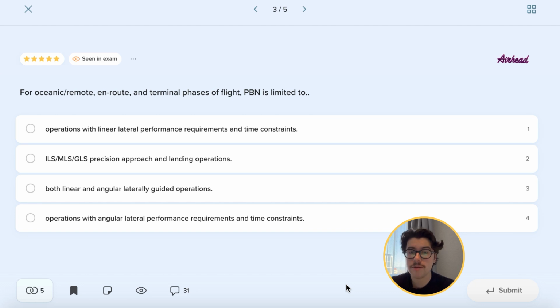And this is also why we use them in approaches, because as we are closer to the station, when flying an ILS, MLS, GLS, and also LPV, which guides you with an angular deflection of the path, having a more sensitive system as you are coming to the runway will be nothing but beneficial, because you will have more and more accuracy the closer you are, and eventually this will allow you to fly to lower minima, and once you see the runway you can complete the approach much safer than if you had just a linear one, as it is with, for example, the LNAV approach.